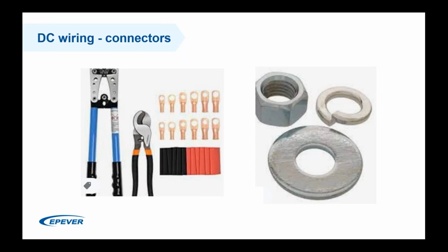And also it's important to note that the tightening torque is also important. Sometimes we break a lock or a part of the wire because we apply a very high tightening torque for our equipment and for our locks, and this is also not good. It's better you use a sort of machine that has a predetermined torque, so that you do not create a resistance variation between your connectors.